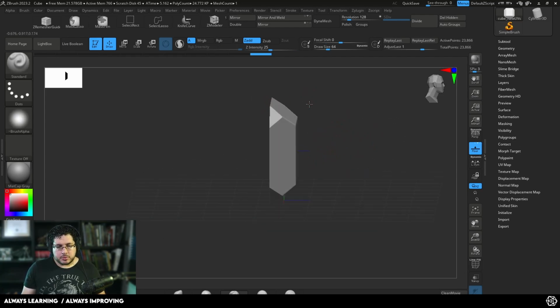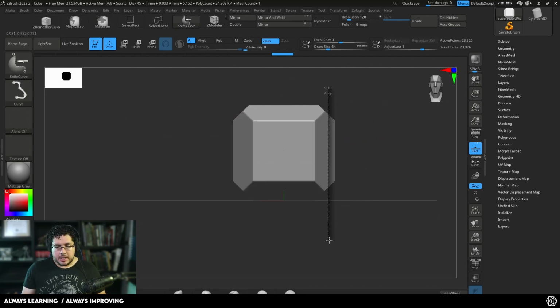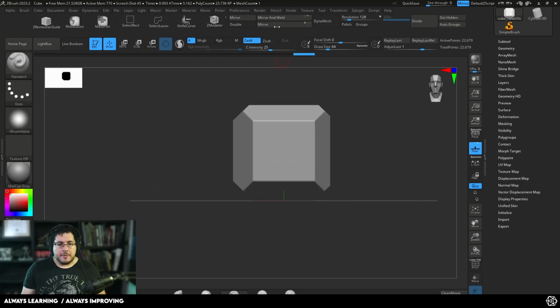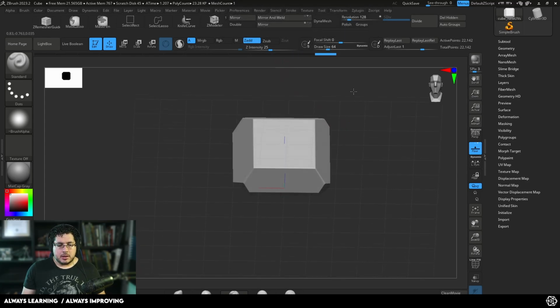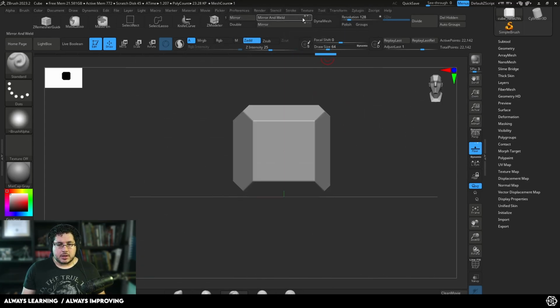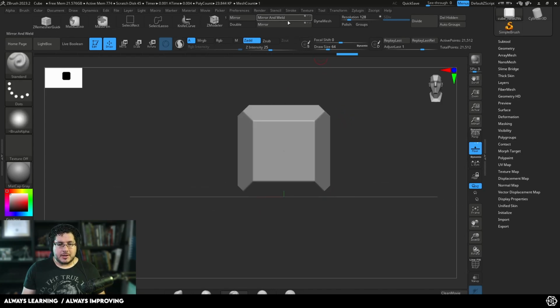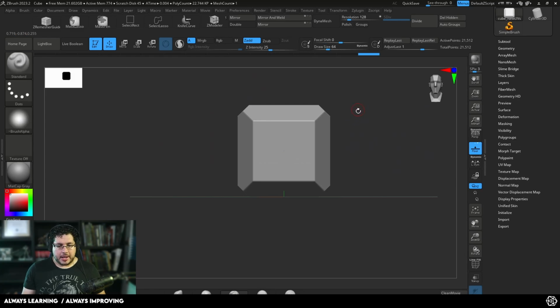Now, I don't like the super thin edges on the top, so what I'm going to do here is, again, I'm just going to cut a line down the middle, and I'm going to cut a line down the side. So you can see that's going to give me another cut right there. And we're going to mirror first on the X-axis. Yes. Well, that's the Y-axis. That's fine. And now we're going to change to the X-axis, and we're going to mirror as well. Oh, actually, first mirror and then mirror as well. There we go. So now we have a straight line going across our whole element.